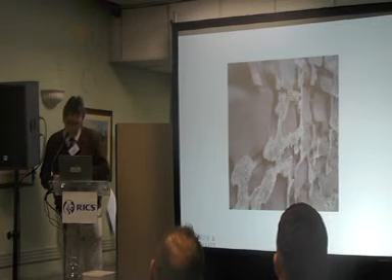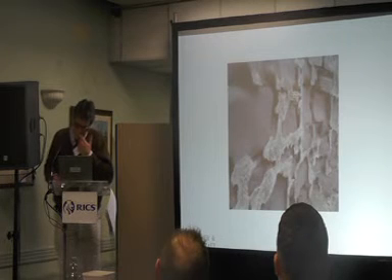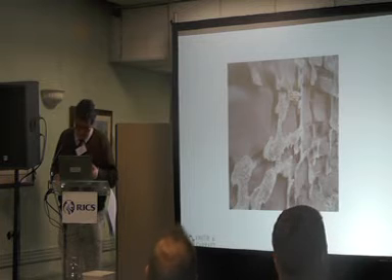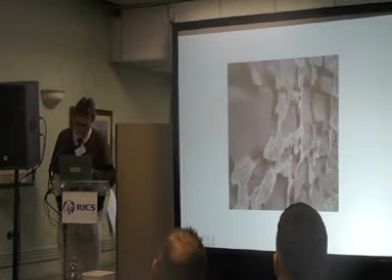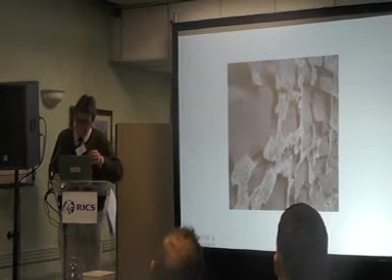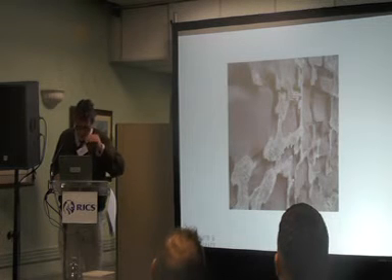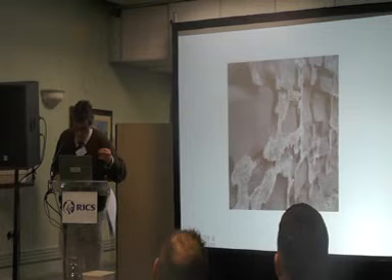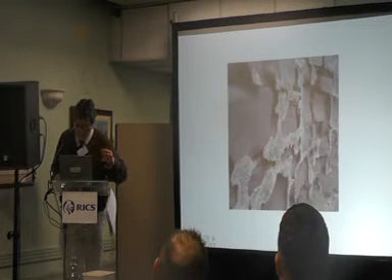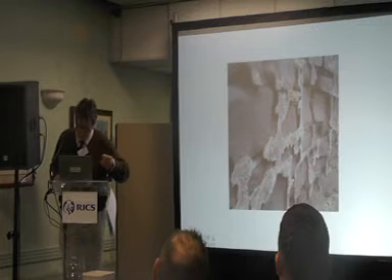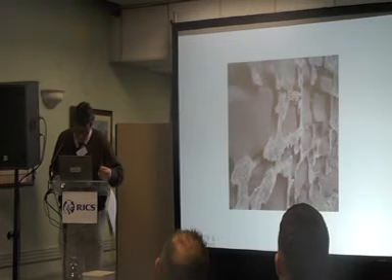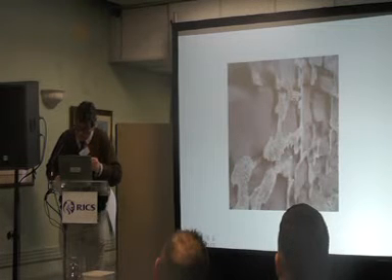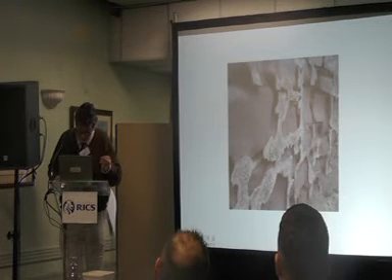There's a wonderful picture. It's just opposite our children's school. That is very advanced decay. You're going to have noticed long before that happens that you need to do something. Look for stones just deteriorating at the edges next to a mortar bed. If the stone is being eaten away and the mortar is intact, it's the wrong mortar. It is much cheaper to sacrifice the pointing and repoint periodically, every 50, 100 years or whatever, than to lose the whole wall. And obviously just a little poke with a penknife will tell you what's going on in most cases.